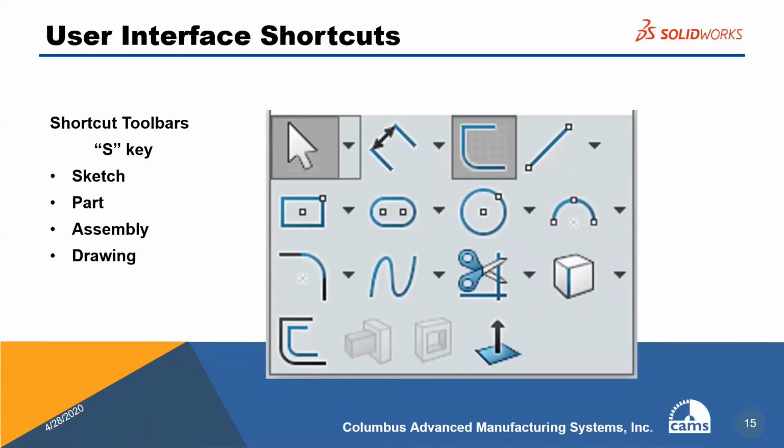So as I was creating a spline, I would hit the letter S, and there's my spline tool right there. Okay, so I could just click on it. I don't have to go up to the toolbar. The purpose for that is that if you're doing this all day long, you're going to find that when you're looking on the model itself where you want to apply this particular tool, you move your eyes to the toolbar and then back down to where you want to use the tool.